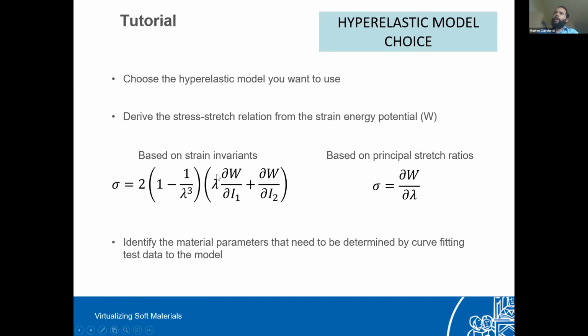So you need to compute this equation, the stress-stretch equation, by substituting the model with n equal to 2, since it is the two-term Mooney-Rivlin model. You have the equation, you put it in here and here, make the first derivative of it with respect to the first invariant here and the second invariant here. Then you should have the entire equation that is still depending on the invariants.